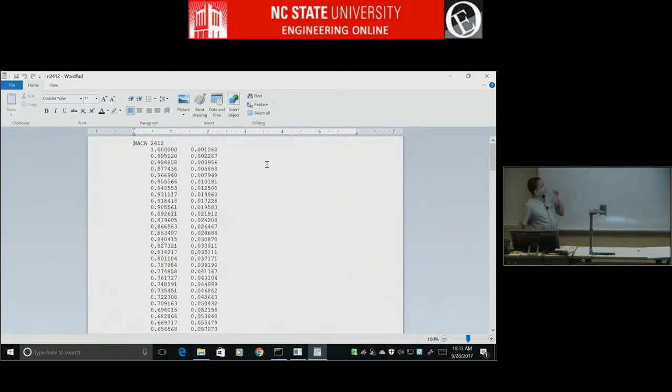So anyway, now you see how the coordinate file looks. This is what Xfoil has created. The top header line is just the name of the airfoil, and then you have coordinates going from the trailing edge, and this is all upper surface. There should probably be 201 points because there are 200 panels. And then somewhere here is the leading edge. For some reason, it didn't put the leading edge exactly at 0, 0. This happens on and off, and it's just the way airfoil geometries are. They won't be perfectly at 0, 0 sometimes. But you can see this is all upper surface, and then you start going to the lower surface now.